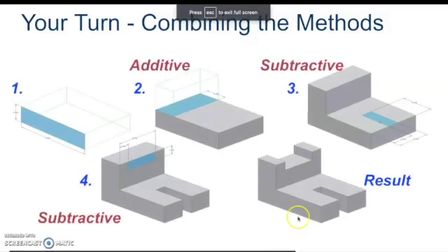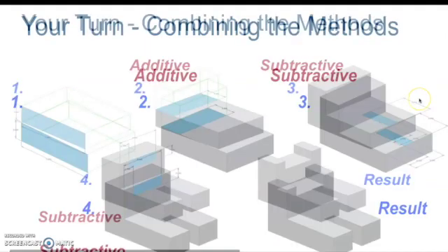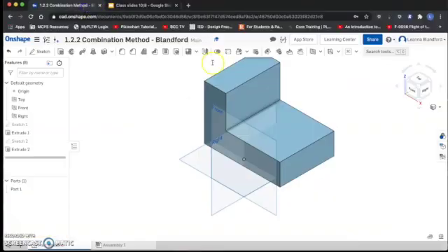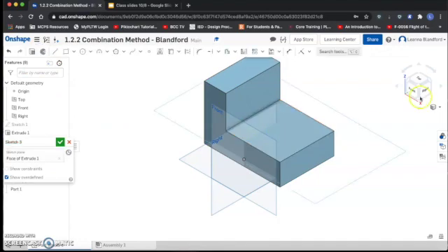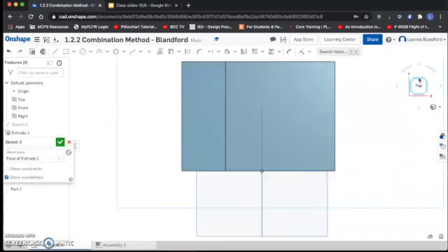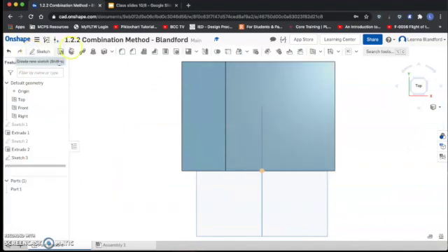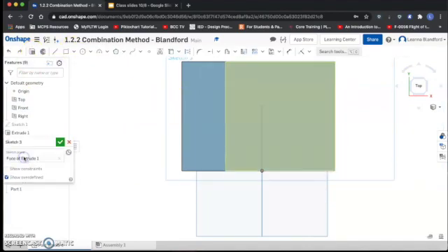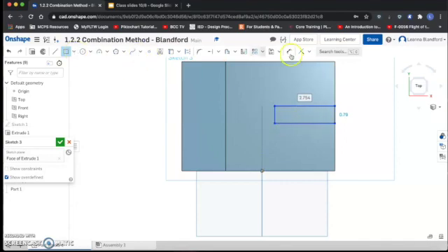So now our next step is to cut out this little 1-inch piece, and that is 1 inch by 3 inches. Perfect. So I'm going to come back over here and start a new sketch on this surface. I'm going to choose my top view again. Oop, wrong tool. Let me open my sketch 3 again. This one's going to create a little bit more dimensioning for us because we have to make sure that this is the right size and in the right location.